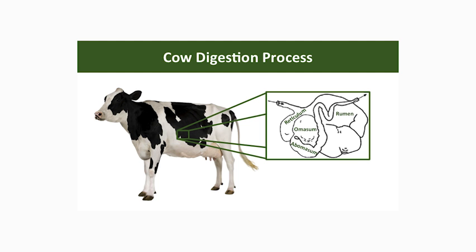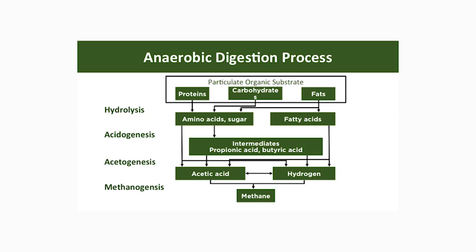The process of anaerobic digestion can be compared to the biological process of how the stomach of a cow breaks down food. Anaerobic processes use available organic matter and are catalyzed by intra- and extracellular enzymes. Anaerobic digestion begins with hydrolysis, which is the breakdown of carbohydrates, proteins, and lipids into monomers such as amino acids, sugar, and fatty acids. The second biological step is acetogenesis.